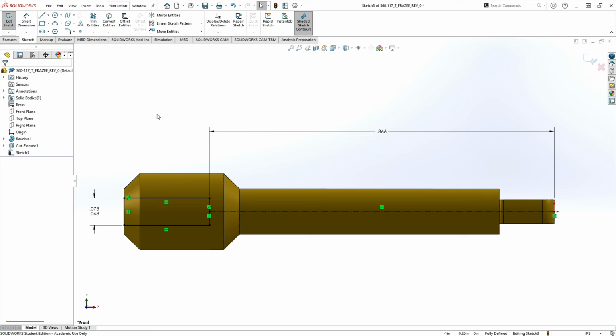Now technically on our drawing we have a center line to outside edge dimension. If we put that in, it'll over constrain the model because we decided to constrain it to center line. But on a drawing you can't imply that the slot is centered, so you still have to dimension it when you get to the drawing side of things.